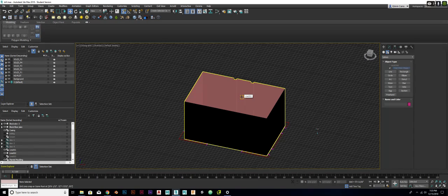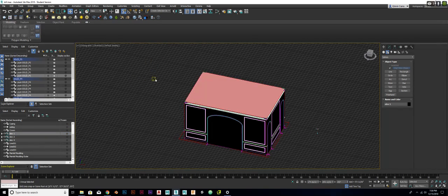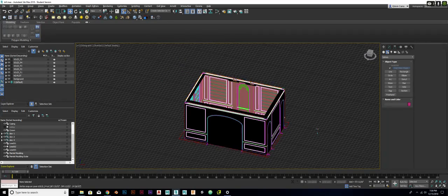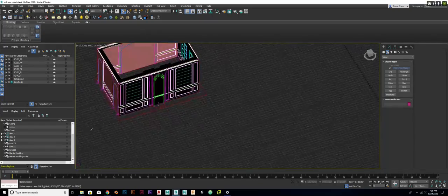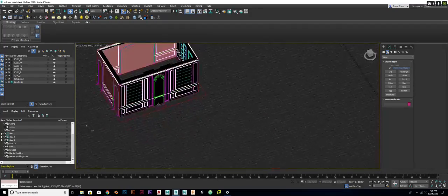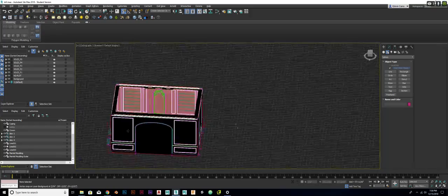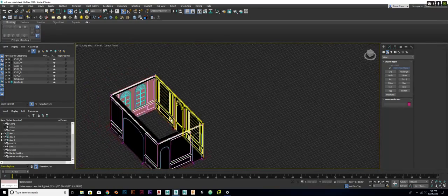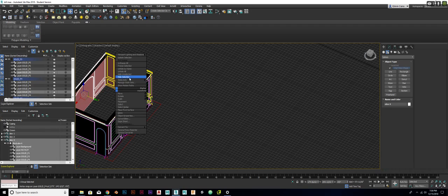Okay, so let's bring back one of our elevations here. Alright, where do we want to start? You know what? I'm gonna do the paneling right now. I think that's the best way to get this to start looking like what it's supposed to be. And I am just going to use, let's say, the smallest panel to start with, because then I just have to scale out to match everywhere else. So we're gonna do the paneling again on that elevation 2. So we don't need that. We don't need that. Let's hide selection.